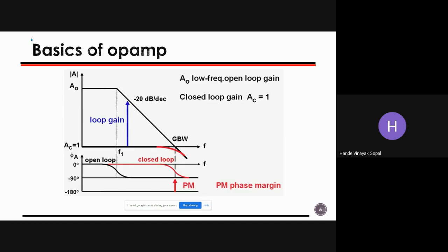That is really how it is, because the moment you start simulating this operational amplifier, you will not reach minus 90 degrees at any point of time, even if you increase the frequency. You will get that only when your frequency is infinity, right? You can just try it. You might have tried also, you will get 89.999, but never 90, as the frequency increases. This is also very fundamental. As you can see, it has only one dominant pole, so we can say that if a system has only one dominant pole, then it is inherently stable.